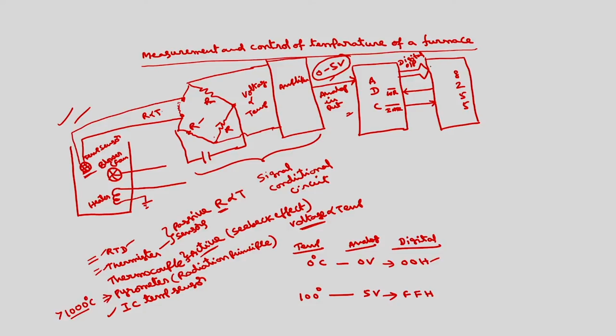This we are connecting to port A. This we have connected to PC3 in our earlier example. This we have connected to PC7. As we have discussed in the last lecture, in order to start the conversion, this WR bar should be a low to high transition. We have to apply a low to high transition at WR bar.